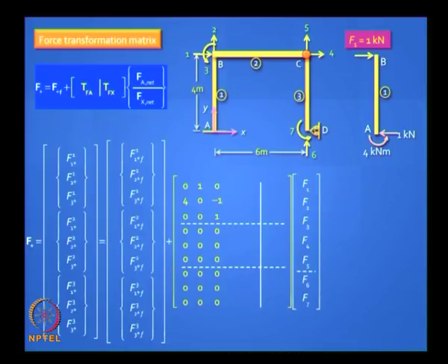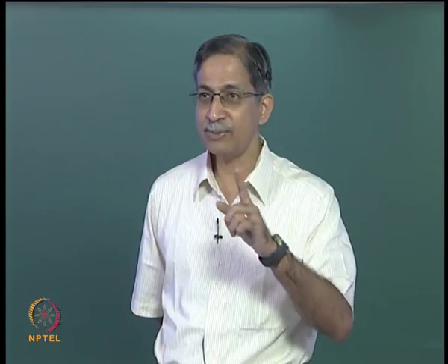I have written down the first 3 columns corresponding to F1 equal to 1, and I will show you F2 and F3 shortly. But if you look at that first column, 0 4 0, is it right? Because only the first element will have non-zero items, the second element will not be affected, the third element will not be affected, because this is a cantilever action for element 1, agreed? So that is why you got zeros here.